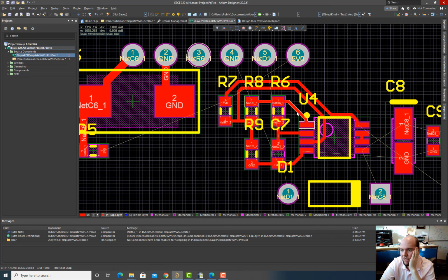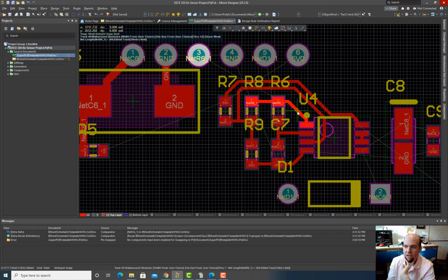What I'm gonna do is click on this wire. I'm gonna have to punch through the board. So while I'm doing the wire routing, I can hit the plus key, and that drops one of these through holes here, vias.